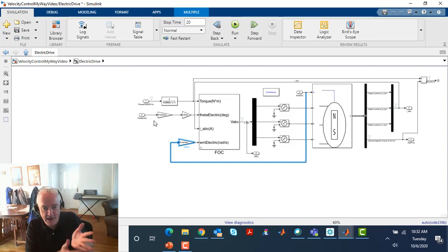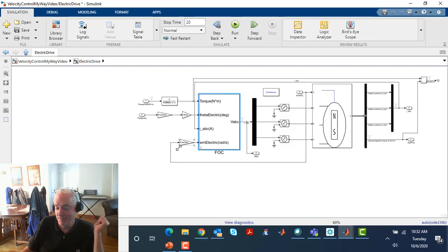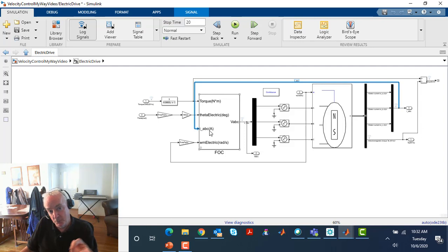We might get into why this was important as we move through this series, or we may not talk about it again at all. Anyways, field-oriented control is based on feedback of what's happening mechanically, expressed by what the shaft is doing, but also what it is doing electrically. Here we'll see feedback on the currents, the A, the B, and the C current. So it's a 3-component signal that expresses the currents flowing through the A, the B, and the C circuitry of the permanent magnet AC motor.